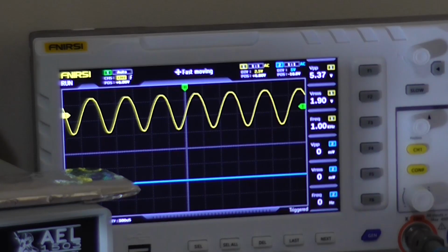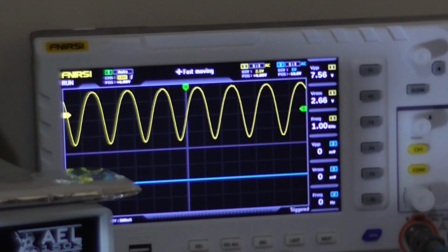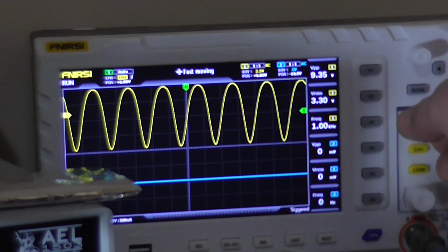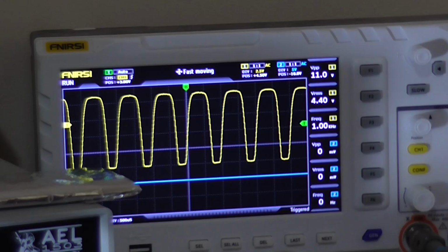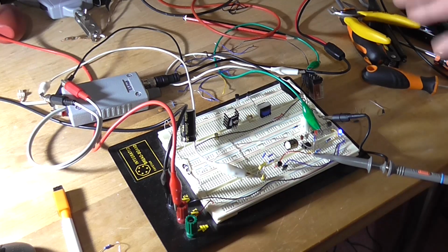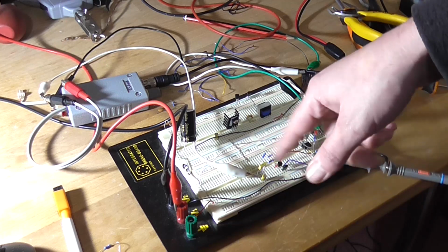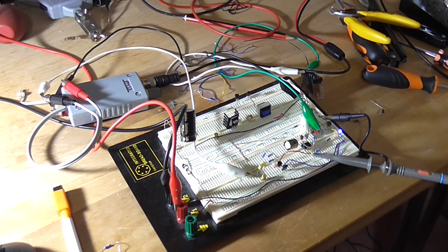And if we look at the oscilloscope screen, we can see that it's a reasonably nice sine wave there. And if I increase the volume even further, well, it's acting as an amplifier, but eventually we're going to hit clipping. But that's fine, because all we need is for pin 2 to be brought to ground potential. So that makes the circuit more viable because the input sensitivity of this is pretty low, which is what we want, because we don't want to be detecting a sound signal at 2 or 3 volts peak to peak before it actually does anything.